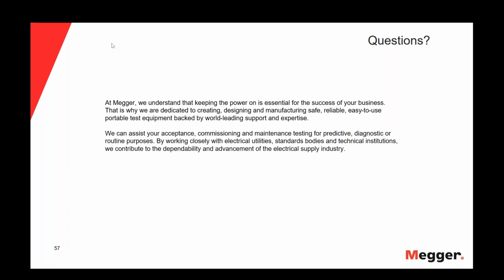Thanks, Henning. So, Robert, are there recognized standards for the tan delta test value? Well, as Javier presented, there are the tables in IEEE 400.2. For comparison and assessment, there are 3 categories: no action required, further study advised, and action required, based on the mean tan delta, stability, and tip up.